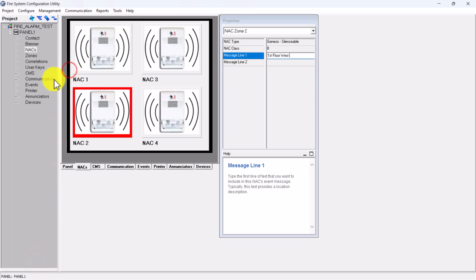And we also need a relay, which is going to be a CR. Now we're using the CRHs for high voltage, so you can connect 120 volts to the CRHs. The CRs is just all low voltage, dry contact. So we have one relay, and we're going to add that device. See, keep making the same mistake. So we select the next available slot, add the device, and boom, we got those two relays inside there.